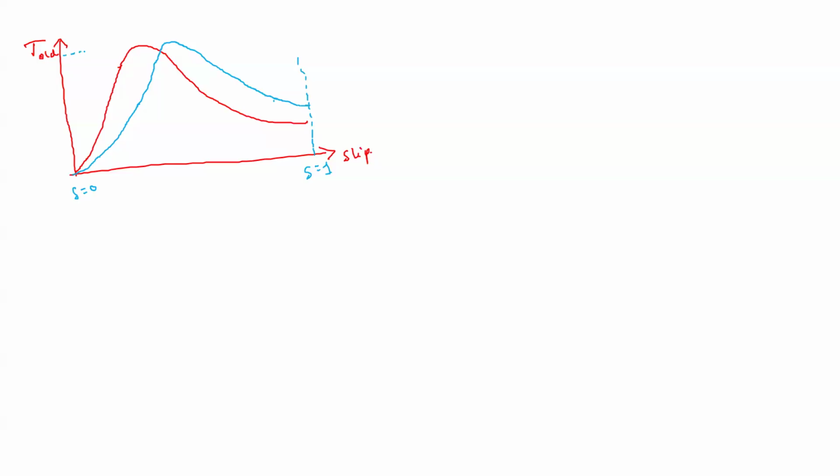So when we added this, so this happened, let me write it with another color. When was this T max happening in the first case? T max is happening at slip equal to R2 dash by X2 dash.